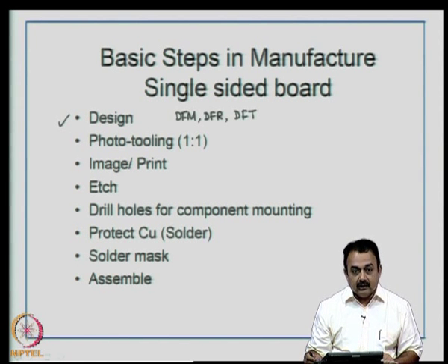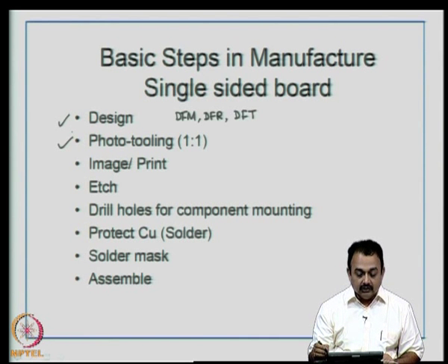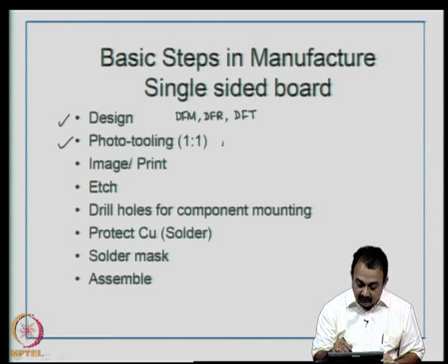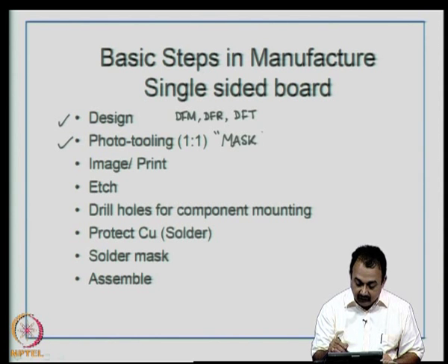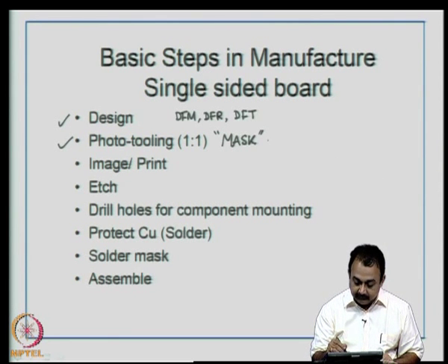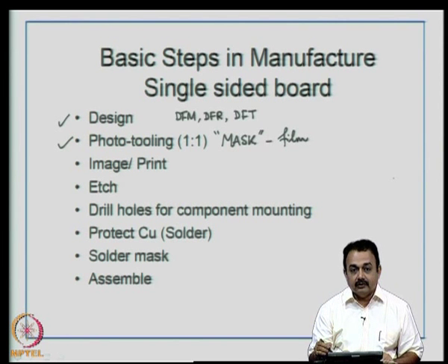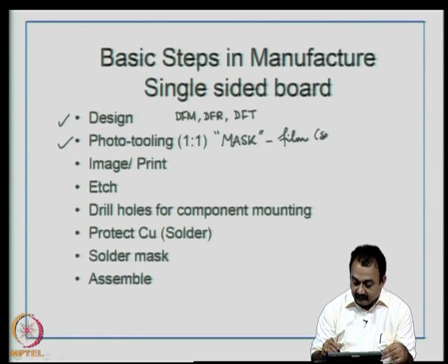Then the design is sent for creating a photo tool. We saw that a photo tool is also known as a mask. So, the output from a design will now be used to create a mask. A mask is basically a film that houses your design or contains the complete circuit. So, you may have to have several masks for a multi-layer board.